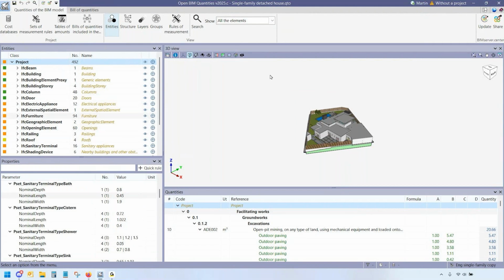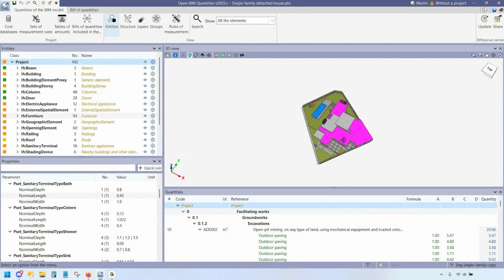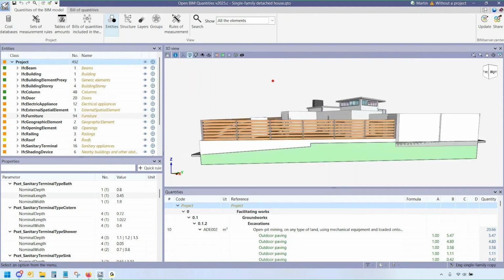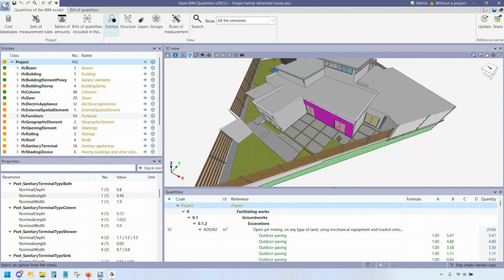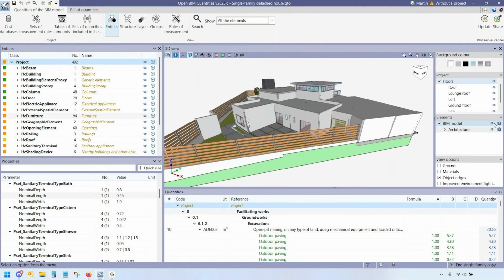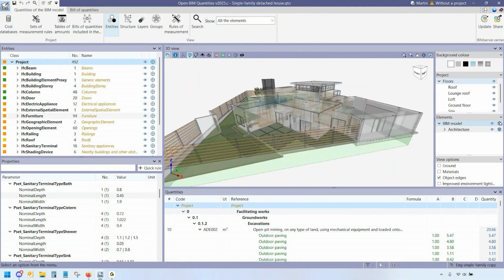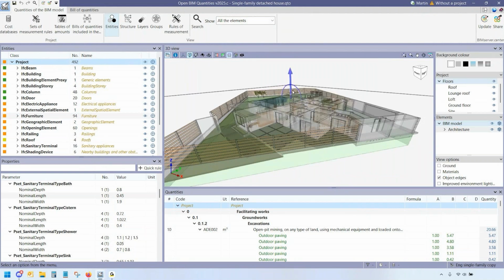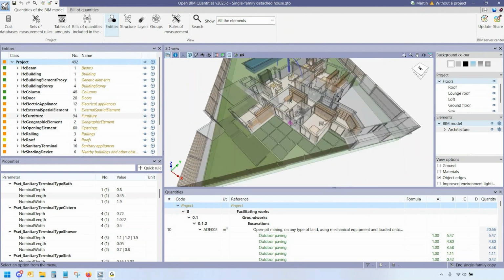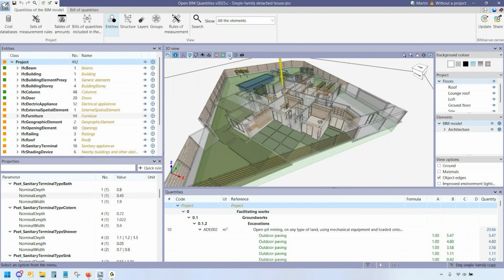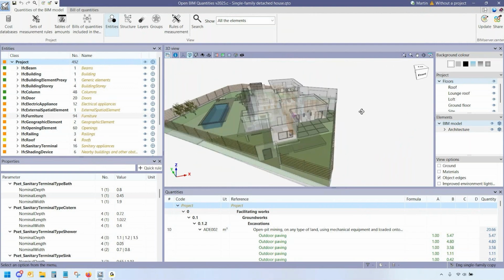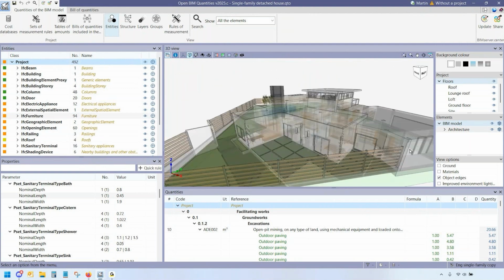So the first thing we have is a 3D view area. I just hold Shift and the scroll wheel on the mouse, and I'm orbiting around. I have tools here to control the visibility of the model. Let's say we want to see through the walls, for example. Well, we have that possibility, or maybe we want to section or plan view the model. We have all kinds of possibilities to visually explore the model.